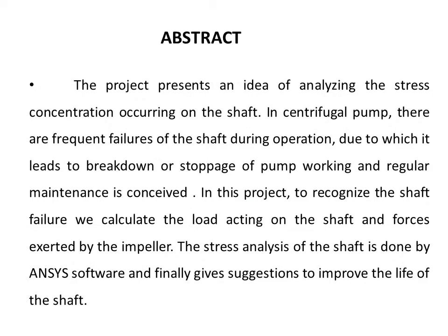Abstract. The project presents an idea of analyzing the stress concentration occurring on the shaft. In a centrifugal pump, there are frequent failures of the shaft during operation, due to which it leads to breakdown or stop of pump working, and regular maintenance is conceived. In this project, to recognize the shaft failure, we have calculated the load acting on the shaft and forces exerted by the impeller. The stress analysis of the shaft is done by ANSYS software and finally gives suggestions to improve the life of the shaft.